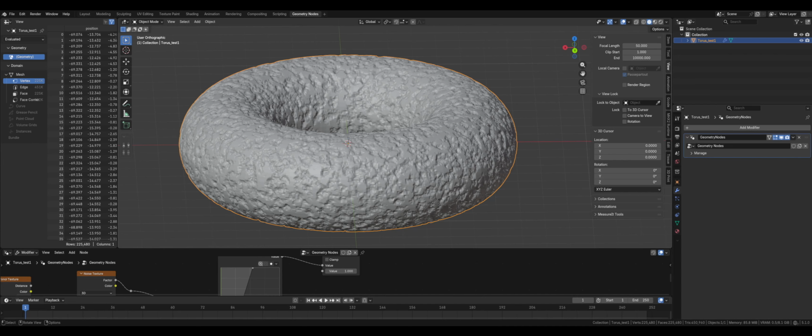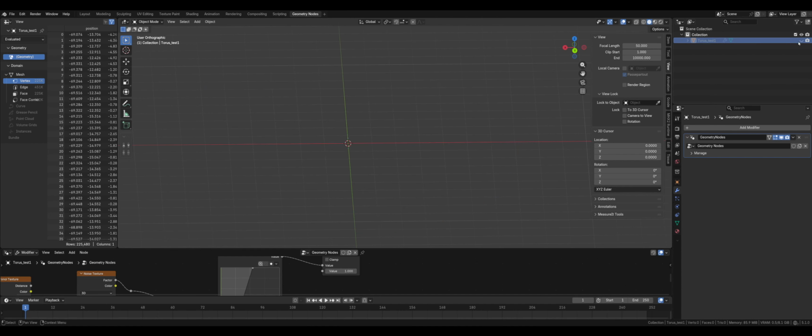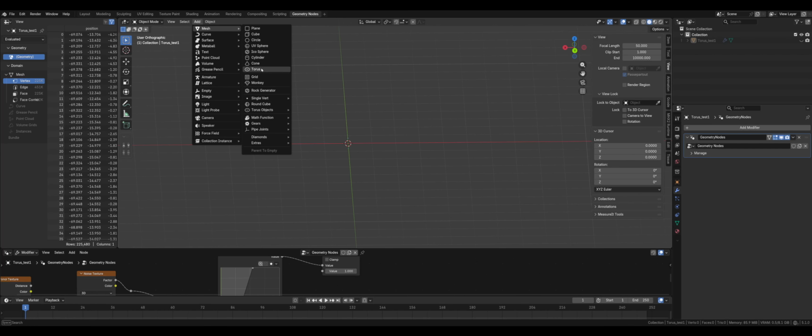Let's start with the basic model that's still three-dimensional. The torus is nice and more interesting than a cube or sphere. You can use the inbuilt monkey mesh, but it isn't manifold to start with, so generally isn't 3D printable. Okay, so let's add this torus.